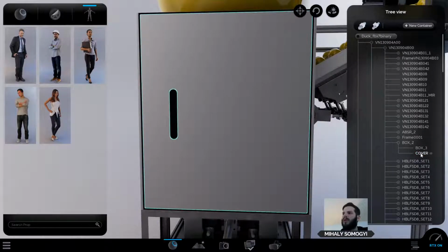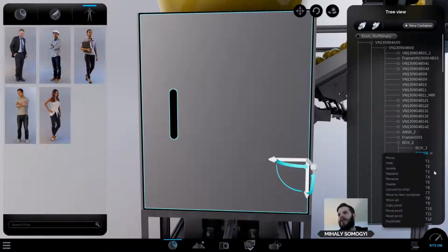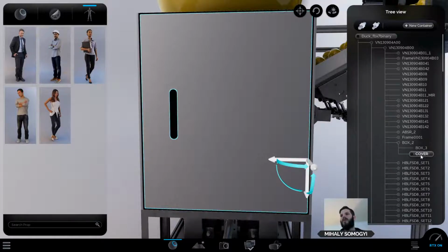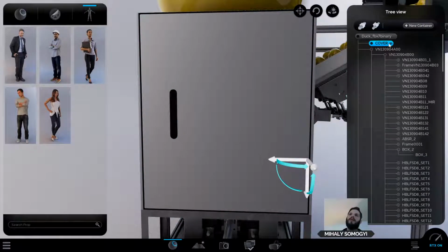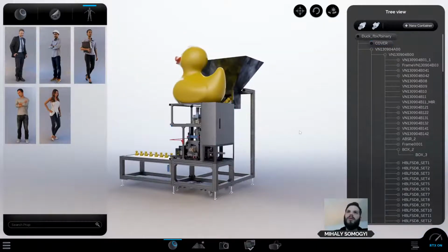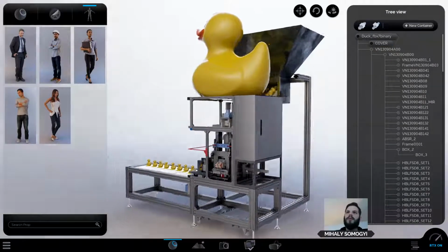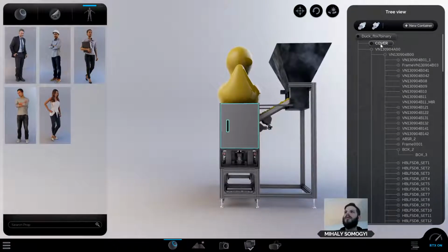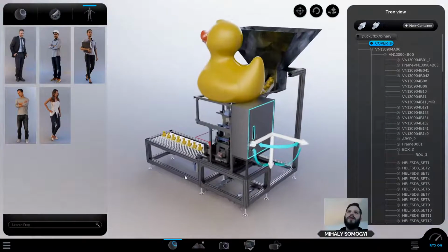Okay, I'm going to convert this one to child. You might see later on why. So I'm clicking right click on the object and select convert to child and drag it all the way up here, so it's easier to find later on. And what is also really cool about the hierarchy is we can assign constraints here.